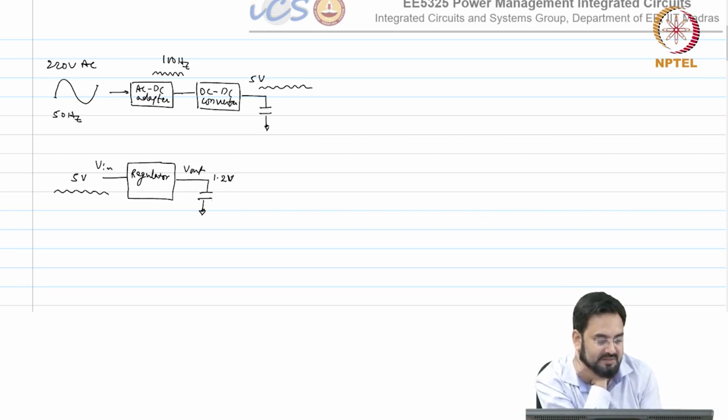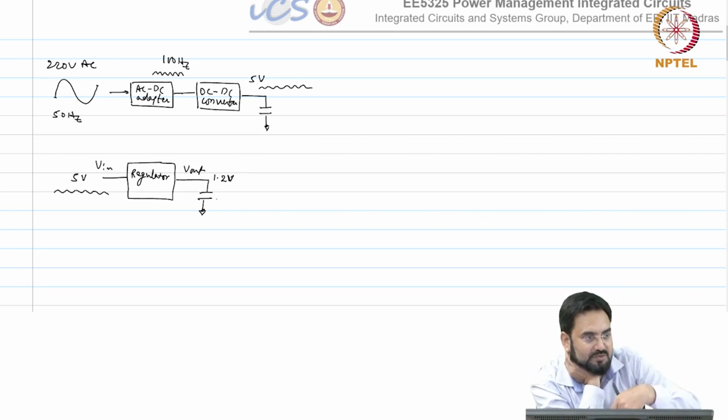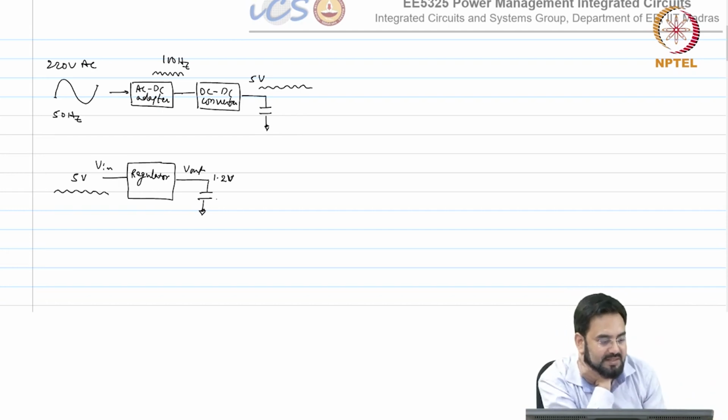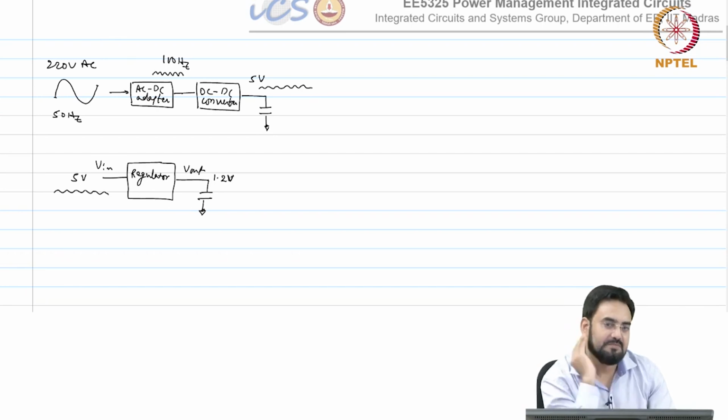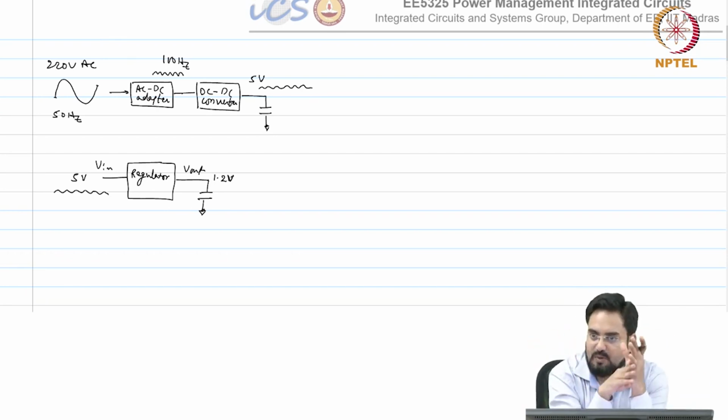okay, because you will get direct filtering from input to output, and so it will behave like a low pass filter. So, making the low pass filter bandwidth lower and lower will reject more higher frequencies, and that will help. But if you are relying on the bandwidth, then the larger the bandwidth is, the better. So, there are two ways to suppress the ripple.